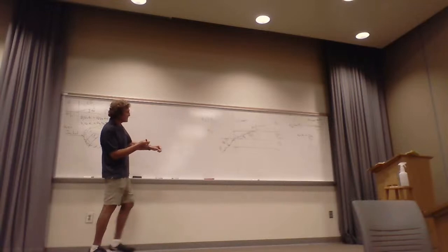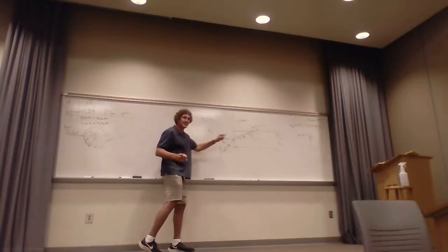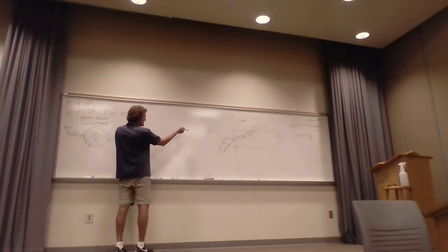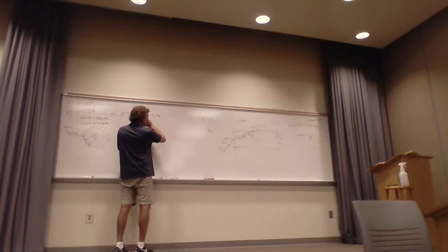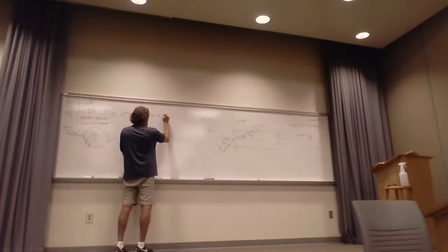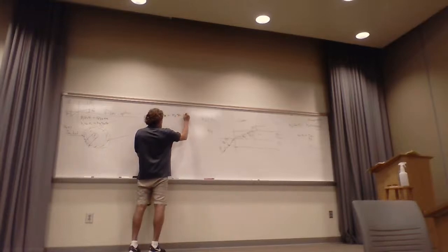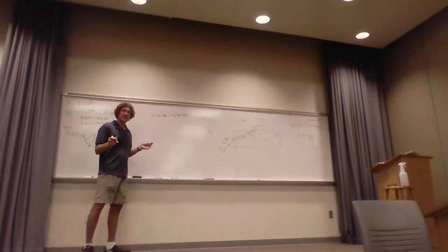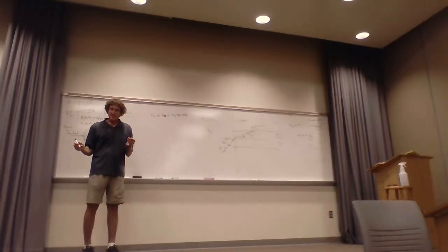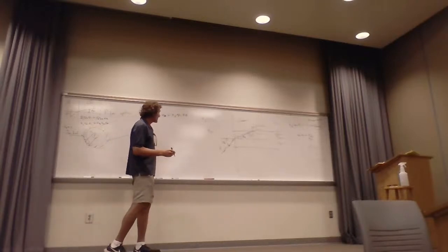Okay, back to this region right here. Now I'm going to use Snell's law there. So I take eta naught times the sine of the angle theta A is equal to the index of refraction of the fiber times sine of theta B. Y'all follow me on this? This is not hard to see, right? That's just Snell's law there. Okay, but here's the neat thing about this.